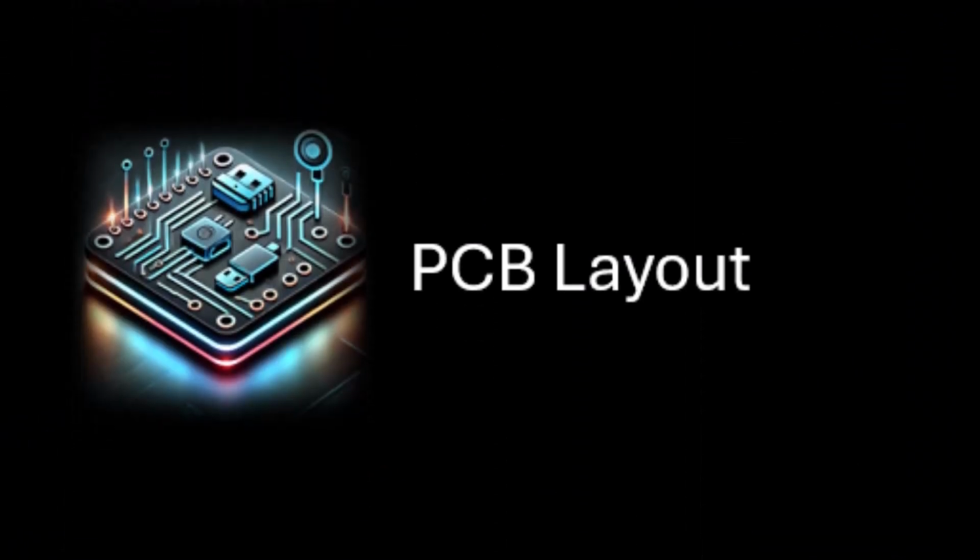Next is PCB layout. So now you have your schematic. It's been approved. You're happy with it. Now you have the task of placing all these things on a PCB, and this is the physical part, right? So you have to place all these things on your circuit board and connect them. This is a mix of science and art. And what I can say for now is placement is really important.